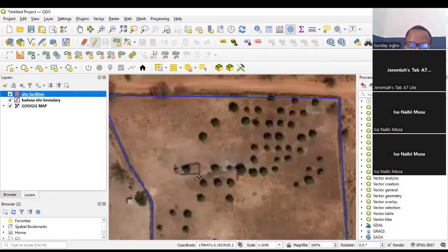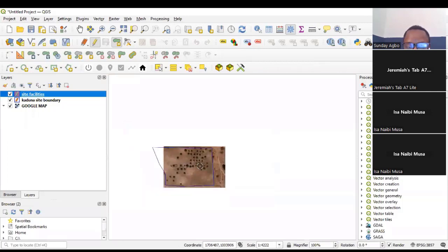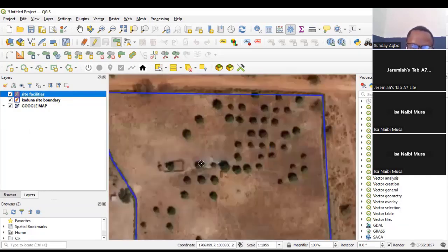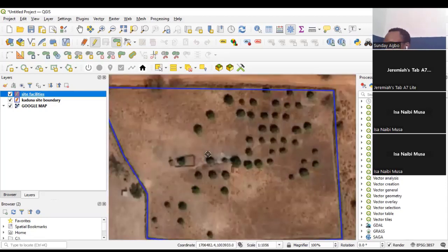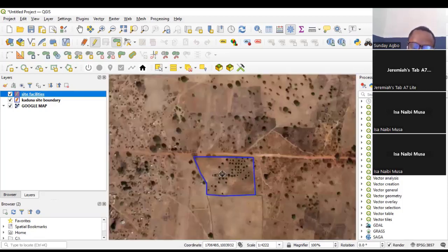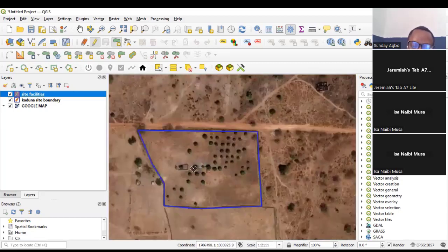Now, if you look at this side very well, you actually see that I think there's a kind of a fence somewhere, which is a temporary structure or going to be demolished. And from the ground here, I see that this particular place is somehow down, like there's a small slopy view here, or a kind of a small hole somewhere here, which is a reasonable assumption because we did not go to the site. But on your own, if you are to do a site plan for any particular site, definitely you need to visit the site or send someone to the site that will pick the position of every other thing that is required. So if this place is a gully area, your field staff or your surveyor will indicate with a point, will pick the point, show the gully area.